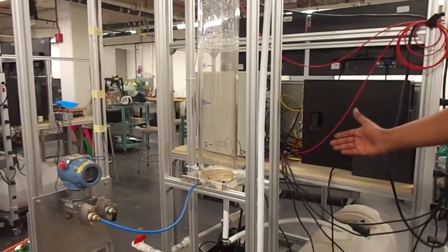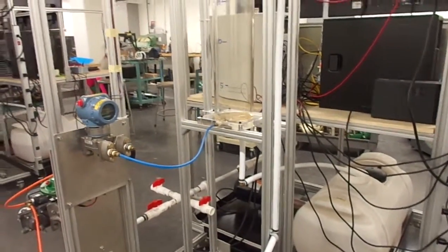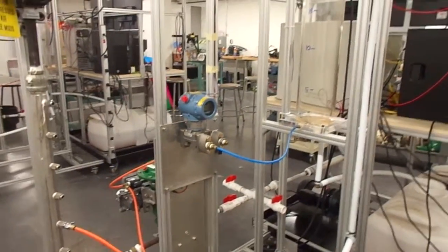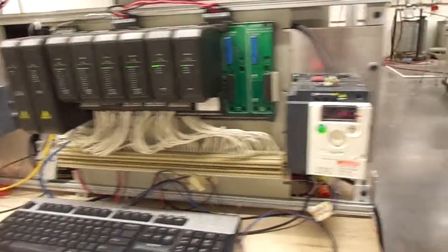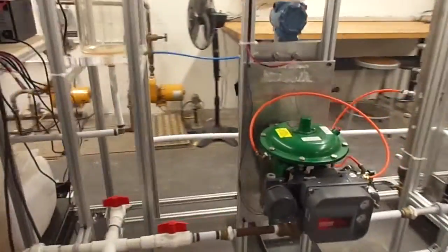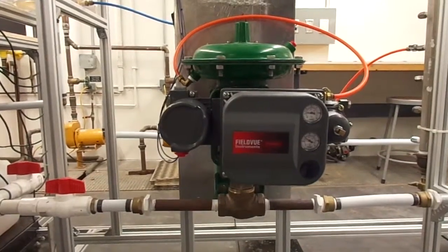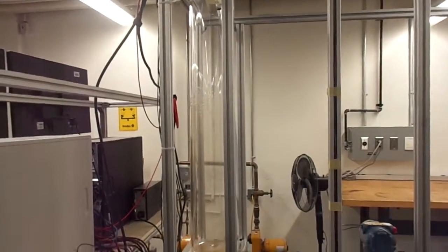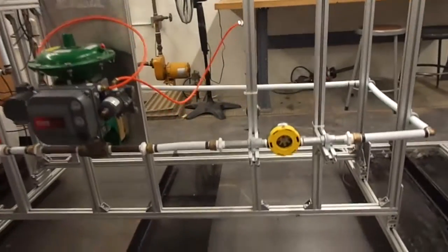This station uses the same pump, a 3 horsepower pump with the same VFD, and it runs on a constant 60 Hertz. Even with that, we have on the other side another control valve with a DV 6200 valve positioner. This is the final control, which controls the level of the tank regardless of the speed of the pump, which is set constant at 60 Hertz. Coming with its flow indicator as well.